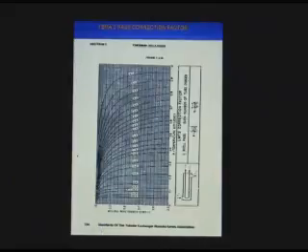Here's a curve of correction factor. There are two other parameters that you evaluate, I'll get my glasses on, the P and R. If you were to look that up on this curve, it would show you the correction factor down here. You never want to be less.